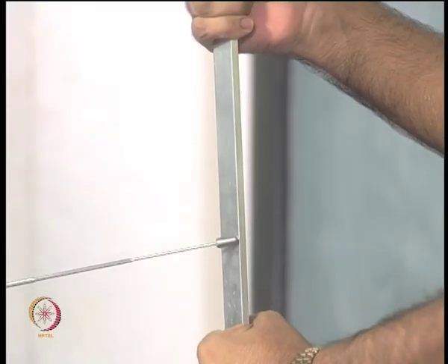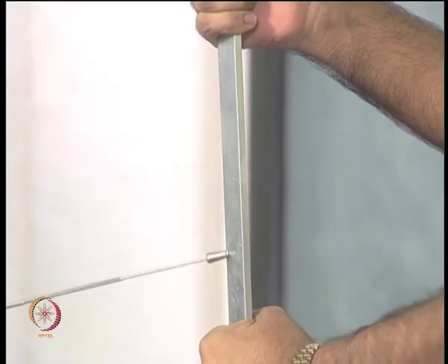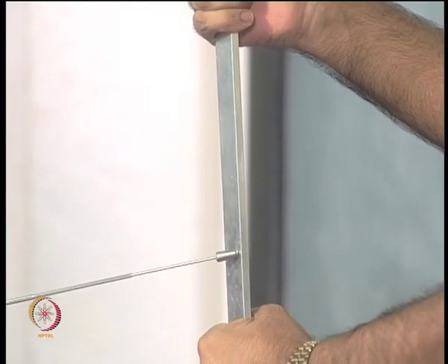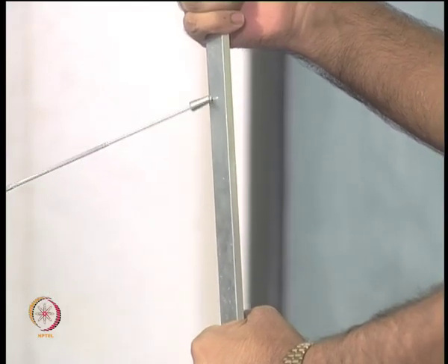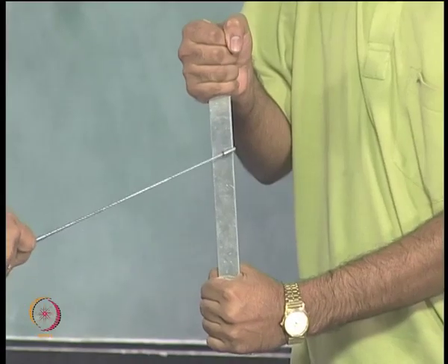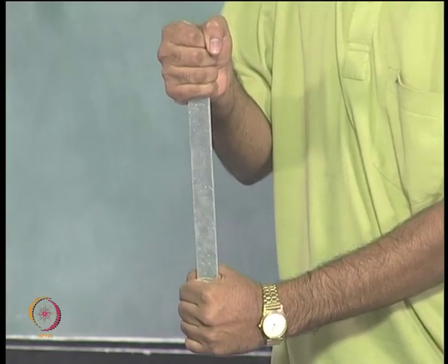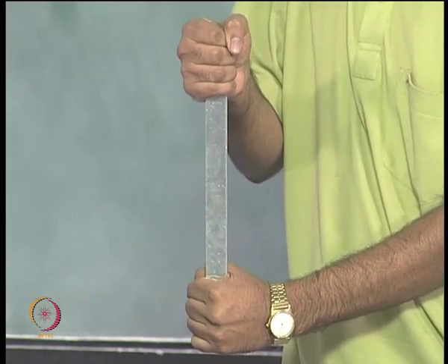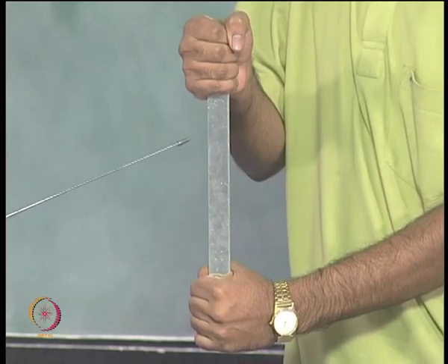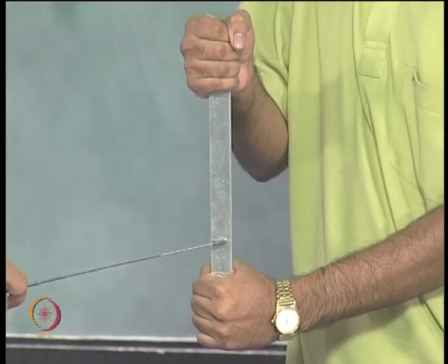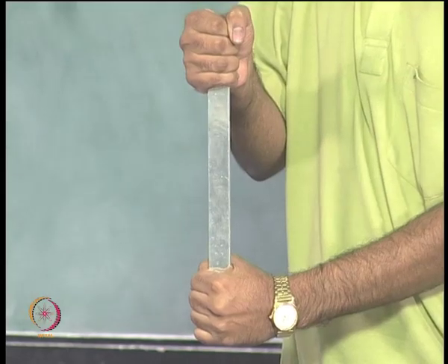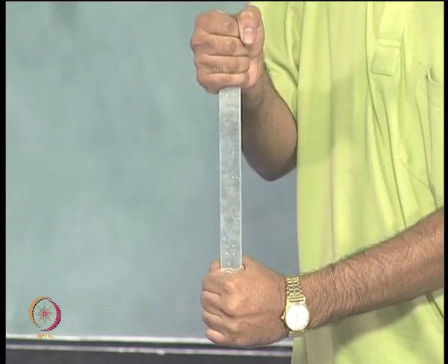And what I emphasized yesterday was you evaluate only a component and you have to learn that you have to put it in a 3 by 3 matrix and put the relevant zeros and understand this as a stress tensor, not just as a stress component. And a problem of this nature, you have a ready made solution without solving differential equations from strength of materials.